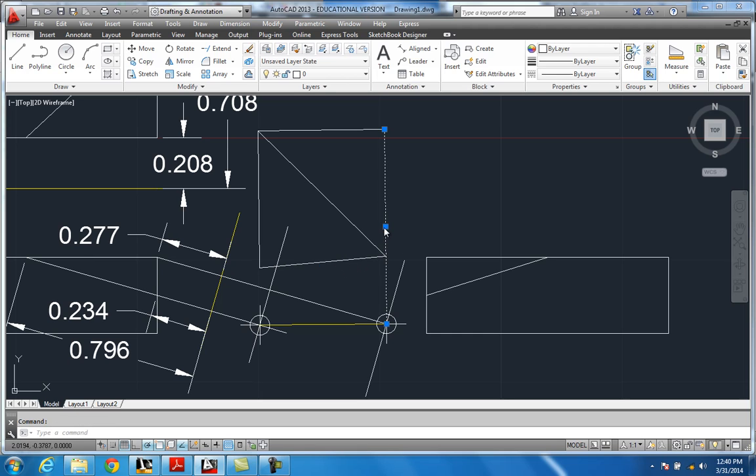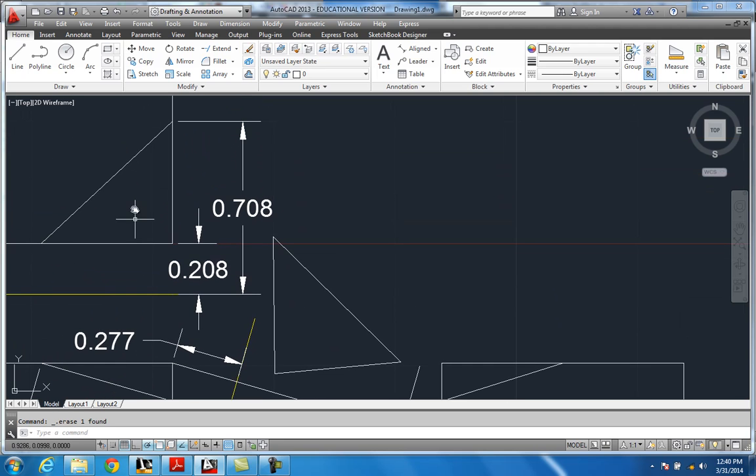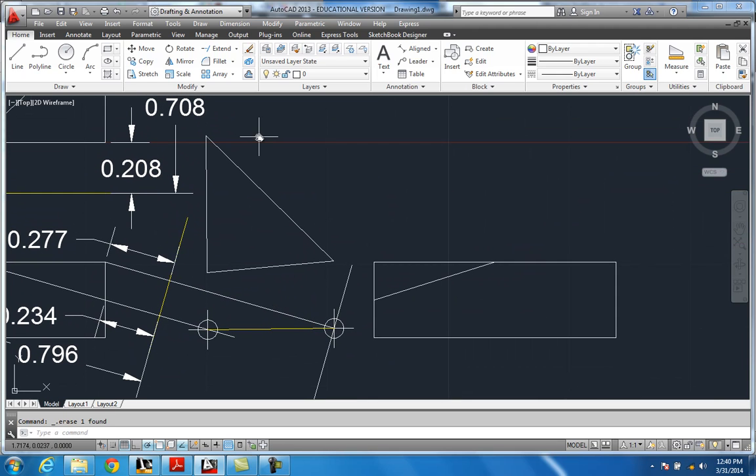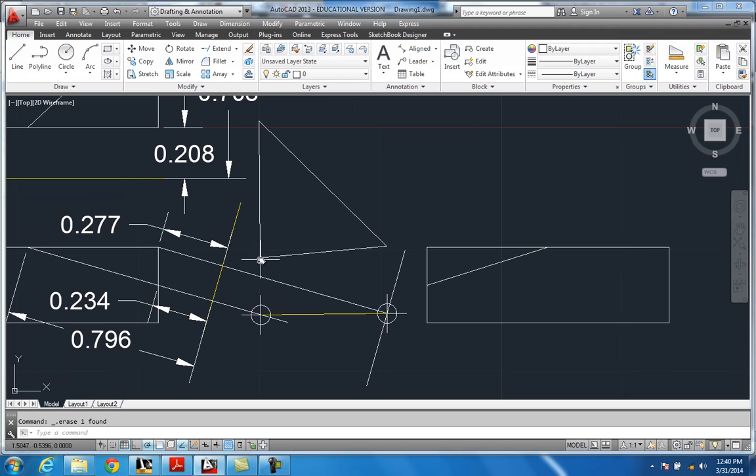Get rid of those offset lines, get rid of this and this. We'll hide that. This right here is the true shape and surface of this oblique plane. So all that we have to do now is just go in and do an inspection on it and find out exactly what the area of it is. And again, this point would be right there, follows this line up to right there, and then this point right here is what it is coming down to this point. And all we did was make us a folding plane line, got us an edge view, and then turned it up. That's where we can see this thing flat.